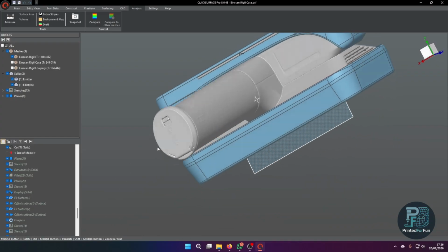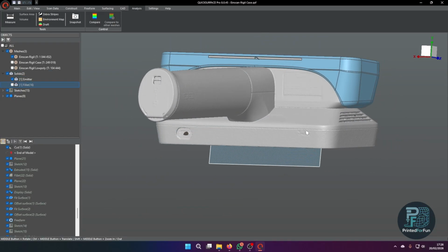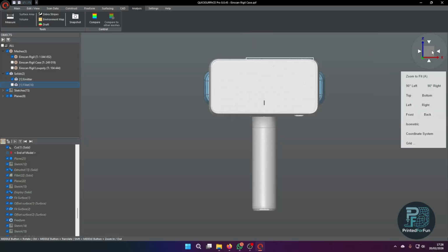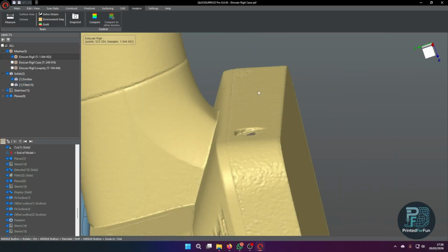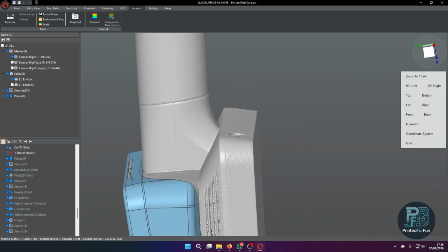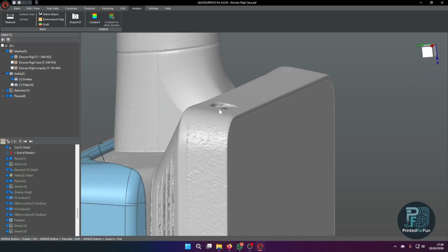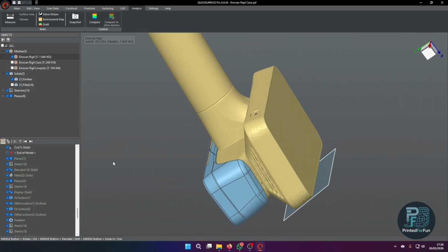The next two steps will be creating some additional cutouts. So here you have the loudspeaker of the scanner and the USB port, the USB plug. Here I had to keep attention that I'm not creating the cutout perpendicular to this surface, but perpendicular to the XY plane, because as you can see, the port itself is not angled to this surface.